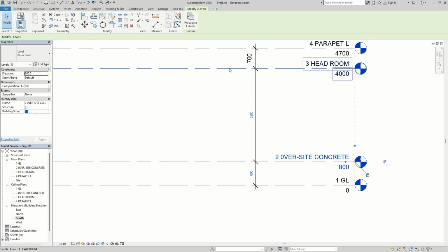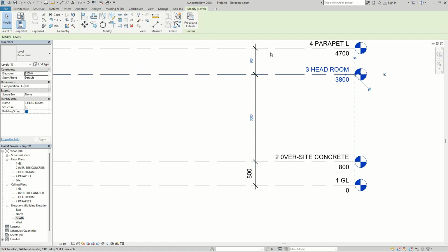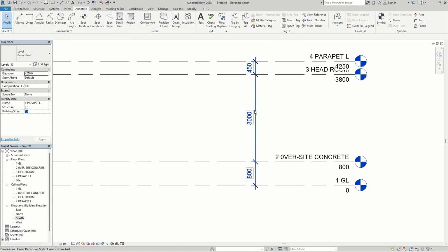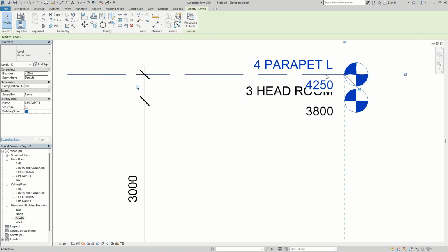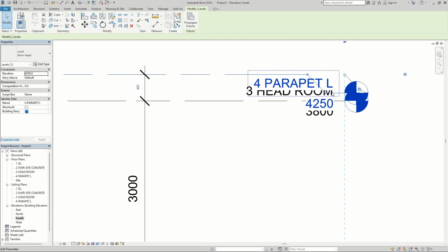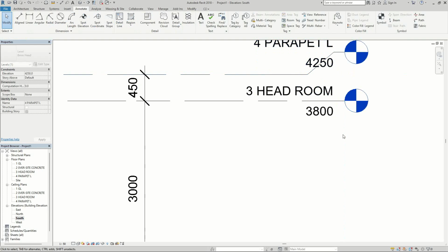So I will come to this next. If I'm clicking on this, then I'm dropping it. So I will enter 3000 as my height and click on this. After considering the design quantities, whatever I will take for my parapet, I will make it 450 to reduce cost. Alright, when you are not viewing the title of this properly, you can select one of these and click on this toggle mark, and it enables you to shift this one for easy view.